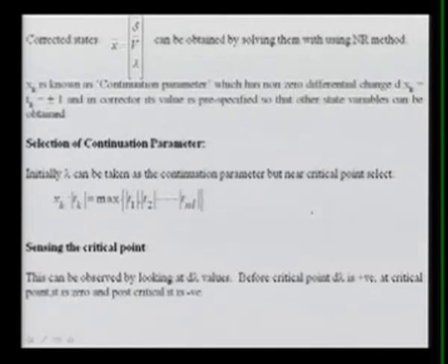If you are going for the corrector and the predictor step, let us see here again. We want this PV curve here. Starting from this point, you have taken a tangent and then you are correcting. Here again you have taken a tangent, you are correcting, and here again you have taken a tangent and then you are correcting. Now you can see the point D, and this is the point E. At the point D, for the corrector step, this will not converge because it is outside, it is not a solvable point at all. So you cannot solve this one.